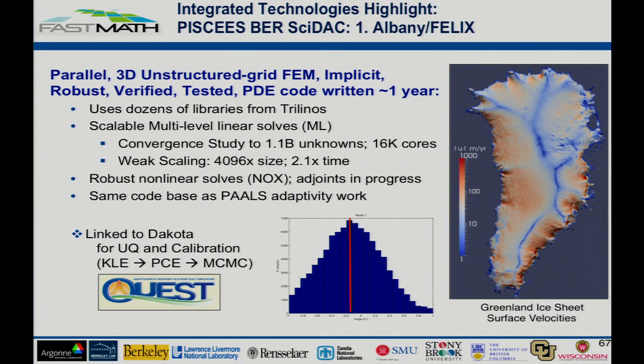We're using multi-grid preconditioning for this. Getting pretty good scalability results. I'll look at that here in just a second. And the code base here is Albany. We're able to link to multiple discretization environments, but the one we're focusing on here is basically the Scorec tools. The combination of Albany and the Scorec tools is the PALS package, which stands for Parallel Albany Adaptive Loop of Scorec.